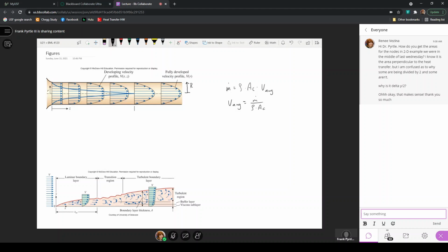So notice here, if I take the point here and the point here, there are different velocity distributions. The velocity is 0 at R equals capital R, and the shape is different for these two positions, and I'll call this position 1 and position 2 here. At position number 1, there's a distribution such that across the center line of the pipe, we have an area where the velocity is uniform around the center line of the pipe.